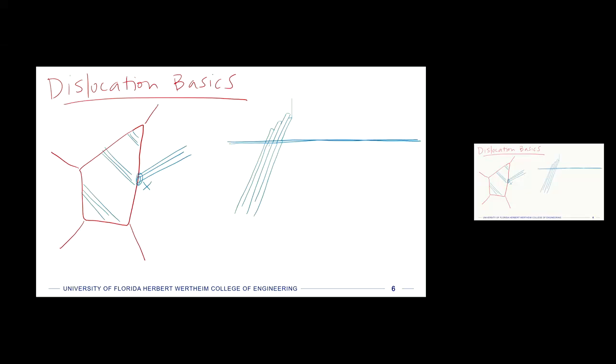And so the slip bands themselves, just to give you an idea of how far these things go, the distance between two slip bands like that would be about 1,000 atomic diameters. So they can be very big in terms of atomic diameters. That's why they could see them coming out, because they couldn't see an atomic diameter, which would be like an angstrom, right?